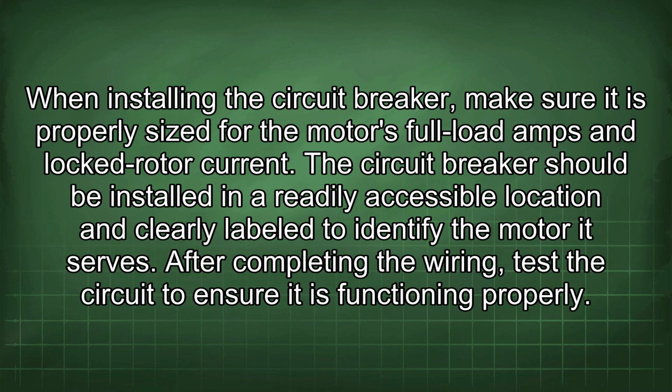When installing the circuit breaker, make sure it is properly sized for the motor's full load amps and locked rotor current. The circuit breaker should be installed in a readily accessible location and clearly labeled to identify the motor it serves. After completing the wiring, test the circuit to ensure it is functioning properly.